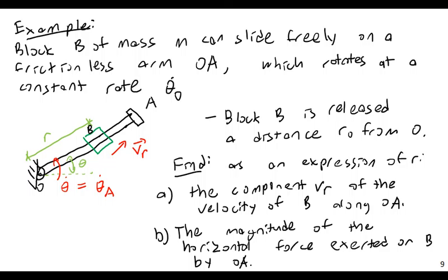And I'm going to go ahead and neglect the mass, or the weight, of the collar for our simple case here. I'm asking how the rod's motion affects the collar. I'm not actually asking for its overall motion, so that's why I'm able to neglect the weight of the collar. Oh, yes, you're right, actually, sorry about that. Yes, it's rotating in the horizontal direction. That's the real reason I can neglect it. Sorry about that. It's rotating in the horizontal direction.